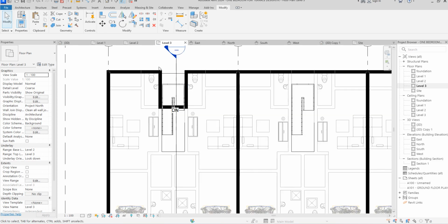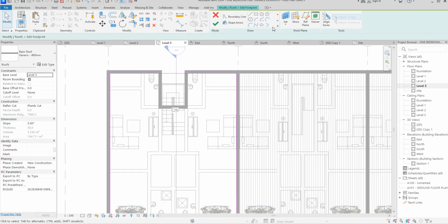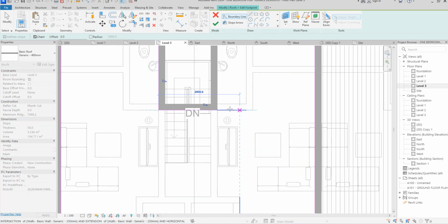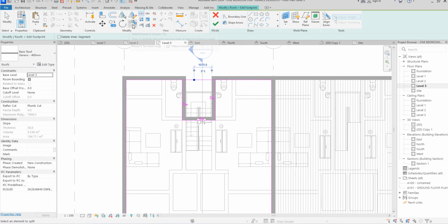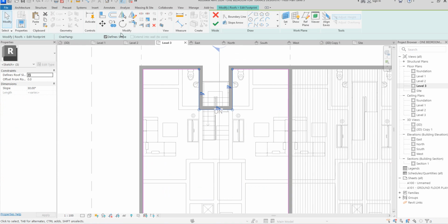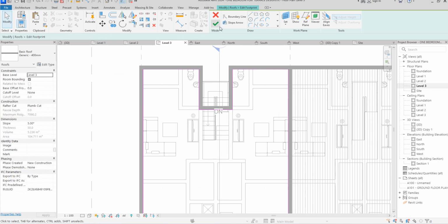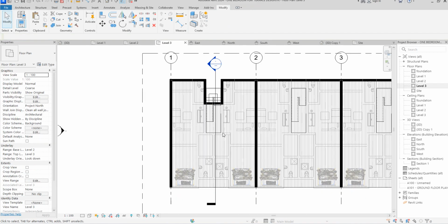Good. So the next thing I need to do is work on this footpath roof plan. I'm going to do that by clicking, then drawing the part for the roof, then splitting this into basic, and I'll do that. Fine. So I'll remove all the slope definitions here. I'll click finish. So no attachments. Let it be like that.